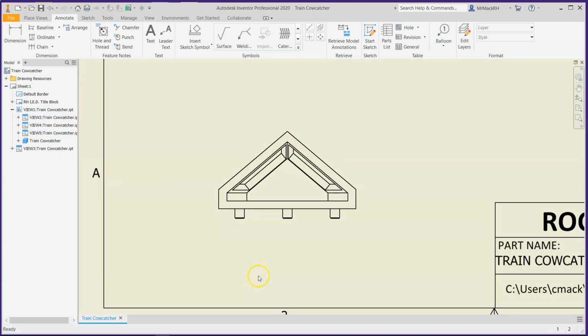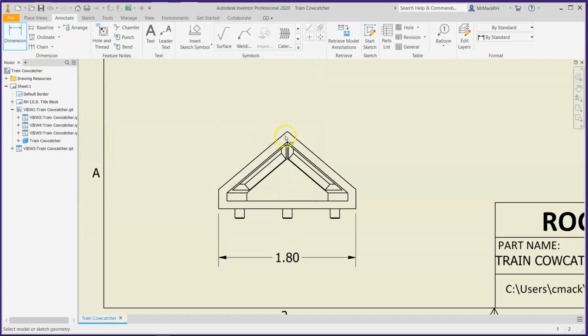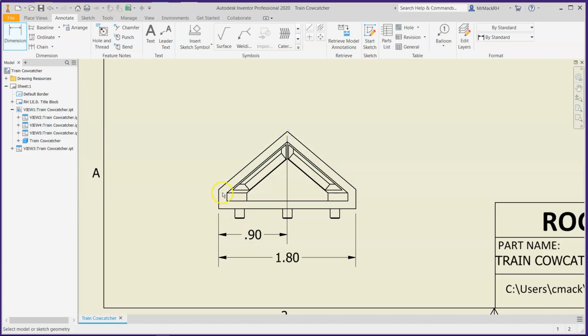I'm going to now do the large triangular shape down here. So we're going to dimension from outside here. I'll go ahead and slide that out 2 notches. Let's go ahead and do the dimension halfway to show that the peak is exactly halfway in the middle. It's mid.